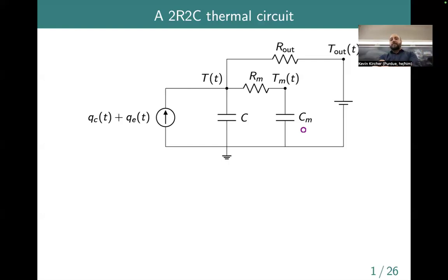Yes. Just going back, when you are thinking about that interior mass, do you also consider people inside the building? So the question is, do you consider people when, for example, calculating what this thermal mass is? Usually not, although I guess you could. You could assume how many people, and then you could just model people as water. Our bodies are mostly water, right? So I guess you could do that. People typically don't in this field, but yes.